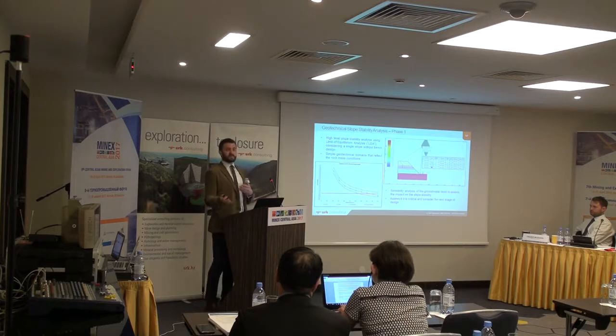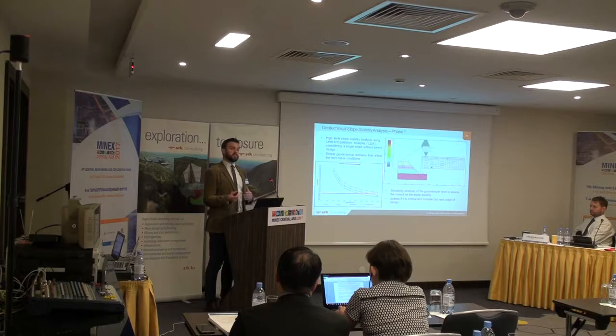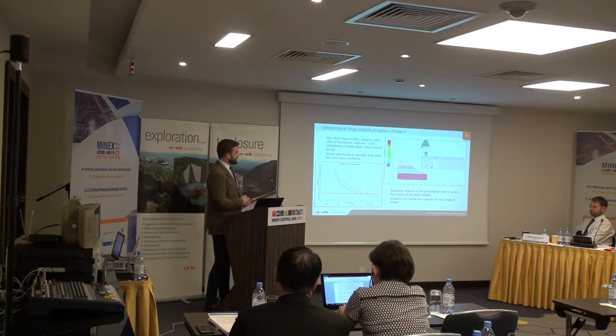For instance, if you're working in a hard rock, competent, low fractured rock mass, the groundwater will have very little impact on the slope stability analysis. And that shows us you don't have to spend too much time on the numerical modelling for the groundwater because it's not very important to the slope design.